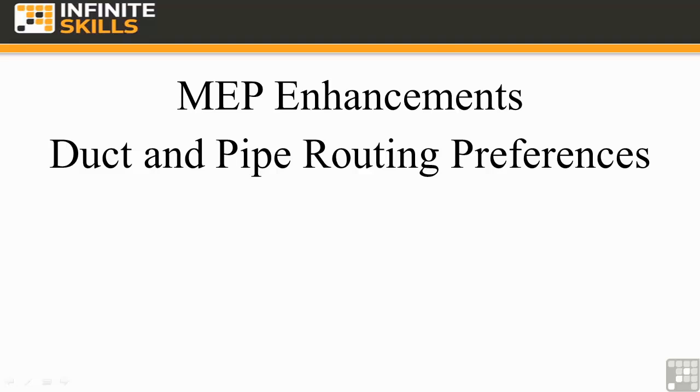In previous versions of Revit MEP, you had to create a duct or pipe type to suit all instances of the types of runs you were creating. So, for example, if your pipe had a specific fitting for a material at sizes 16 to 40mm, and then another fitting from 50 to 100mm, you'd have to have two different pipe types. In Revit MEP 2013, this is handled by segment. Let's take a look at that.